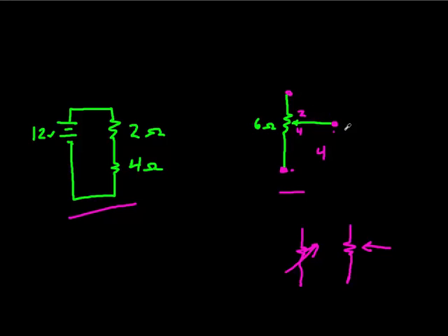So 2 ohms here. And let's just say you slid this thing down just a little further, the wiper, you turn the knob, in other words, you might end up with 3 ohms of resistance on the top here and 3 ohms of resistance on the bottom here. And if you continue sliding this wiper down, or in many cases turning the knob, you might end up with, let's say, the opposite of that, 4 ohms up here and 2 ohms down here. If you kept sliding it, 5 ohms up here, 1 ohm down here. If you kept sliding it, you could slide it all the way to the point that you have 6 ohms on one side or 0 ohms on the other. And if you turn the knob completely the other direction, it would do just the opposite. In other words, this becomes a short basically, and then all the resistance is going through this side of the wiper. So that'll become important here, but the same voltage divider rule applies.